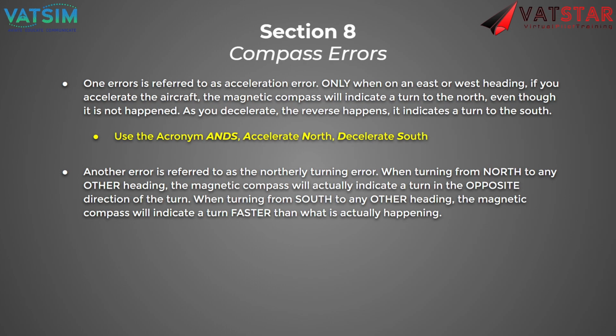Yes, I have a question. Sure. For how much time does it indicate the error in both? Sure. So the rule of thumb is half of the latitude at which you're at. Let's say you're at 40 degrees north latitude on the Earth. If you cut that in half, you get 20. You can expect that error at 40 degrees north latitude to exist for 20 degrees. So you halve your latitude, and that's how long the error is persistent for.